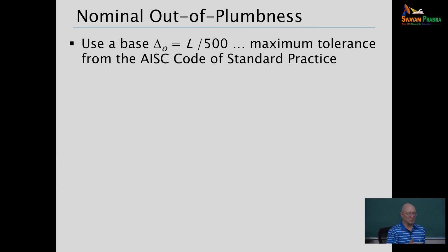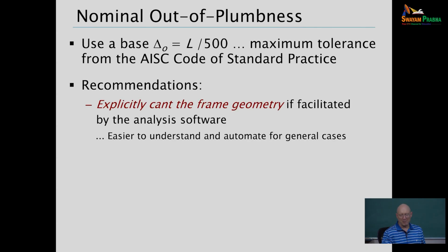And Eurocode would typically have a larger notional lateral load as well, to try, through a larger load there, to pick up on some of those other effects where we're losing stiffness and so forth. And so how do we apply this? Well, what I always have told engineers is that if I've got software that will actually put in the imperfections for me, I'm going to use that.